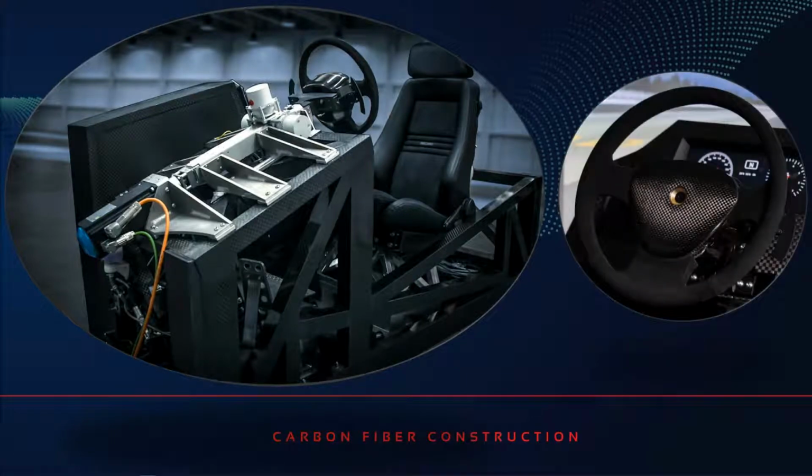The steering wheel itself is made out of carbon fiber and is very light and rigid, with no rim modes below 200 Hz. The steering wheel is covered with a thin layer of Alcantara material to provide the realistic feel of an automotive steering wheel, while still transmitting controlled and accurate levels of vibration. In this picture, you can also see the steering motor over here on the left, which I mentioned a minute ago. This is a professional grade steering motor used in all of our driving simulators to provide realistic steering feel and feedback.